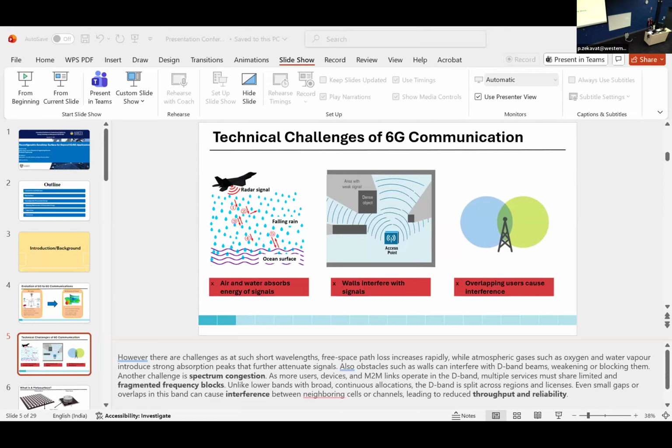So looking ahead, the next stage of this research is to focus on advancing from simulation to practical implementation and real-time adaptability. So first, by integrating Python with HFSS simulation, this can automate parametric sweeps to generate large, realistic datasets. And then this will enable machine learning models to predict and optimize metasurface performance in real time, improving the design efficiency. Second, hardware prototyping and experimental testing will validate the results.